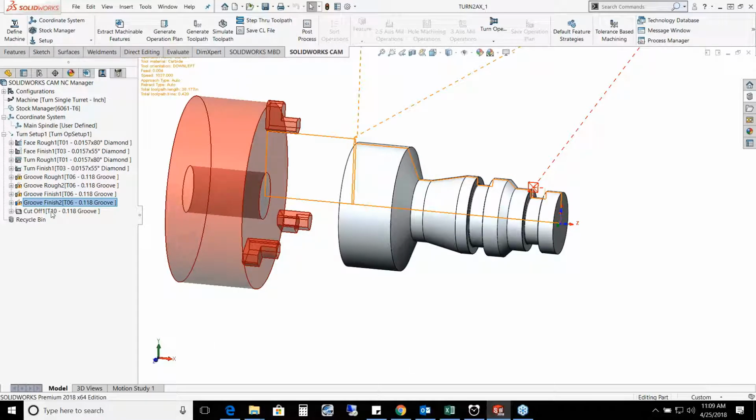I have my cutoff move. Usually it is at the last. That's usually the smart place to have it, because otherwise it falls into your machine in the middle of things if it's not there. So buyer beware, make sure your cutoff moves are generally at the last. That's just where they tend to go. Unless you're on a sub-spindle machine. Sub-spindle machines can come in and pick up off like an OD on the face of the part, do a cutoff move, and then do back work on the back side. And CamWorks has the capabilities of doing that as well.